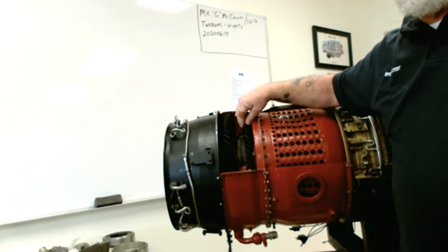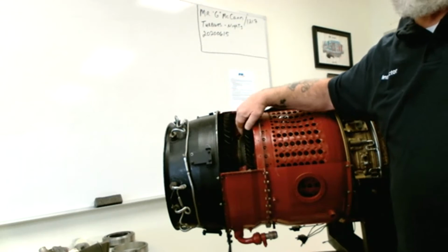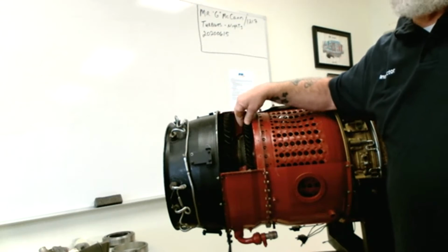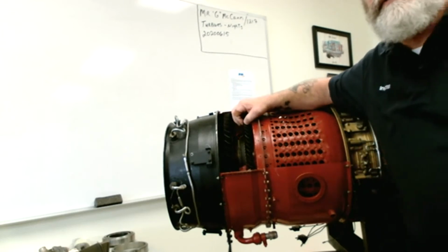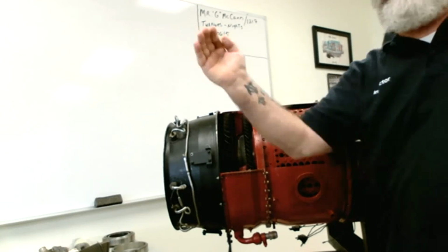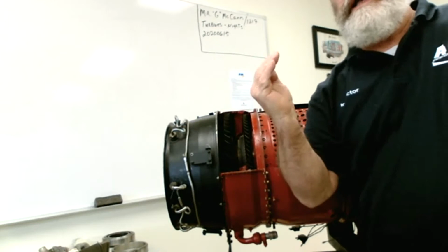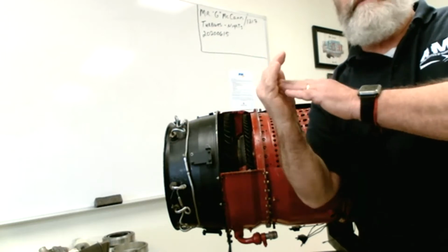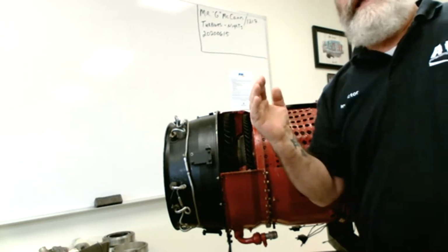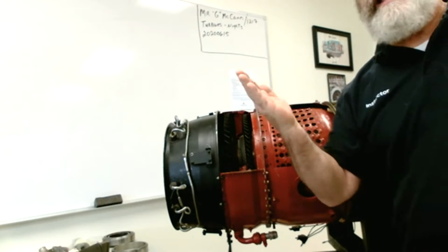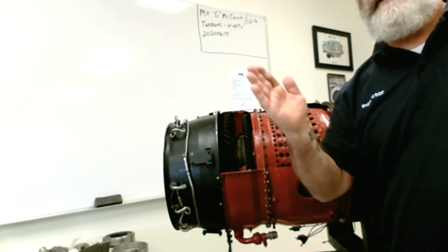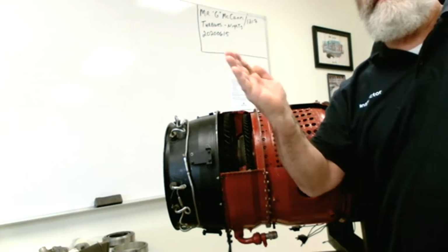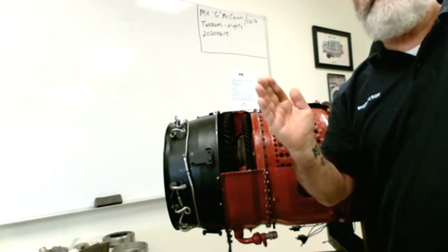All right? The other thing is, we haven't covered this in class yet, but there's more to know about this, right? These blades come in different designs. The three types of turbine blades, and you'll see this in your quizzes, and it will be part of the class, are these. They have an impulse blade, which was used early on, and has a shape sort of like a bucket, all right? Later they came up with an aerodynamic blade, which resembled more of a compressor blade. It just looked like an aerodynamic blade profile, right?